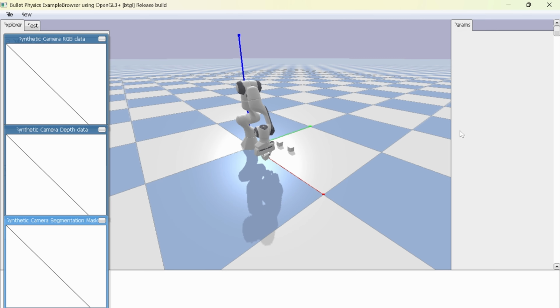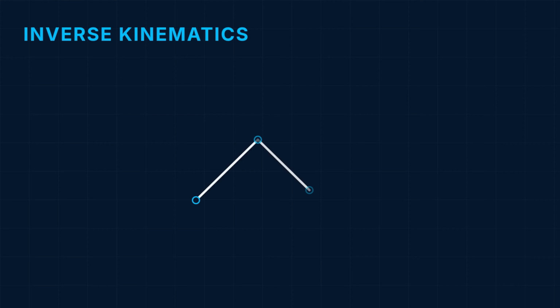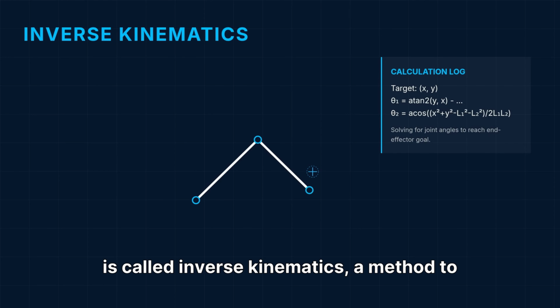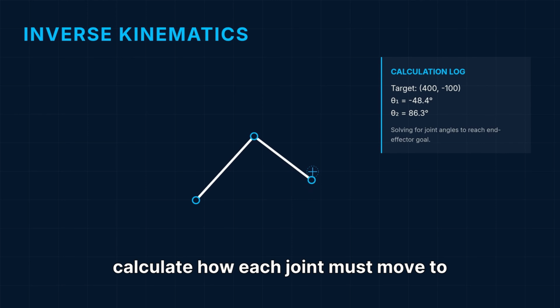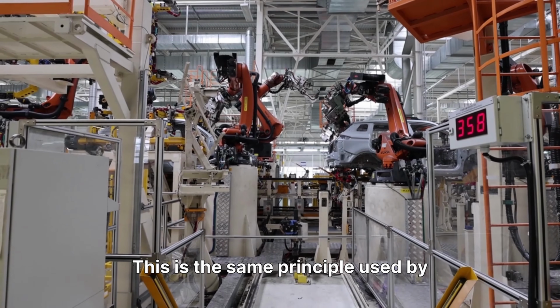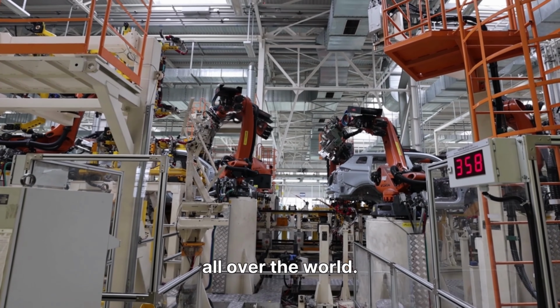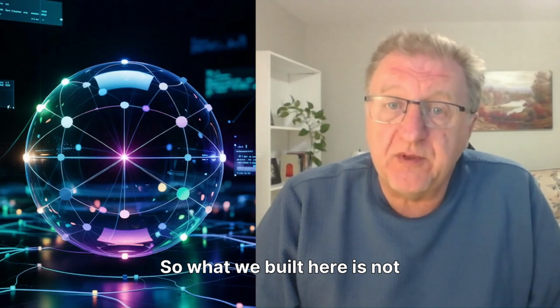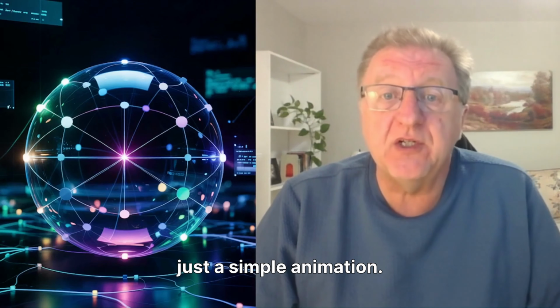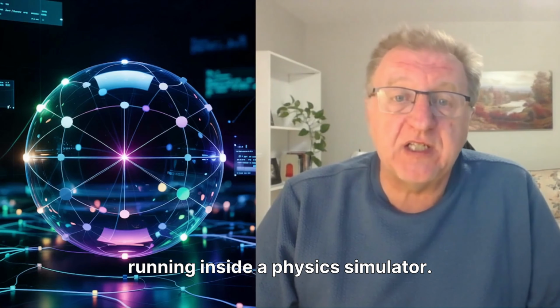What makes this particularly interesting is that all of this behavior is controlled using mathematics and algorithms. One of the key concepts used here is called inverse kinematics, a method to calculate how each joint must move to reach a specific position. This is the same principle used by real industrial robots in factories and warehouses all over the world. So what we built here is not just a simple animation. It is actually a robot control system running inside a physics simulator.